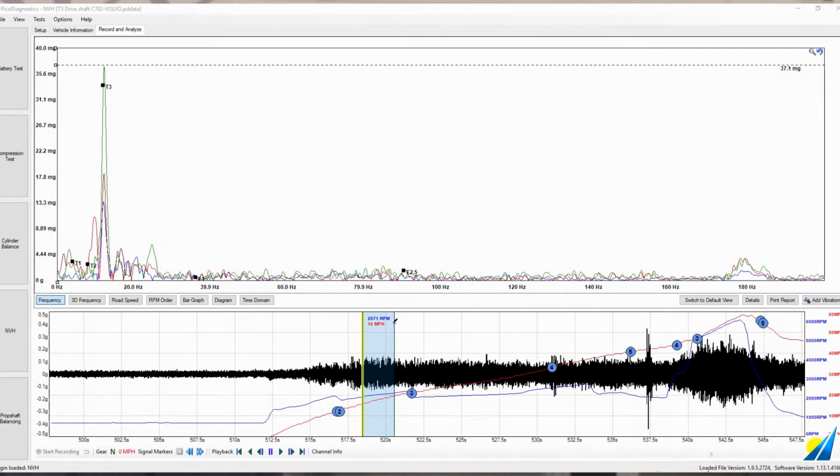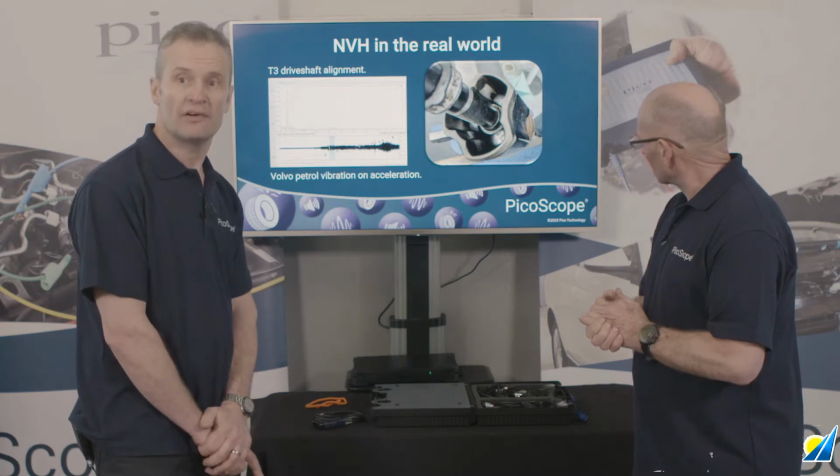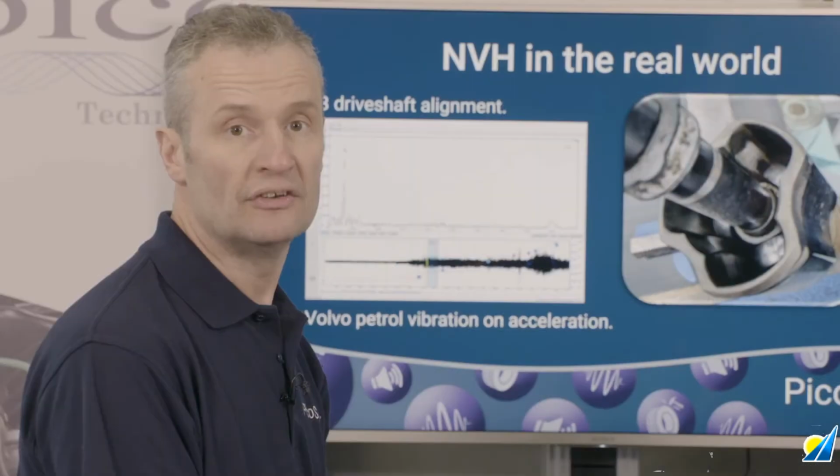The fault here was the inboard coupling of the drive shaft, so it's a tripod style joint. Now think about the fundamental frequency of this shaft, that would be the same frequency as T1, component rotating at tyre frequency, but on the thrust surface of the drive shaft we've got excessive wear. That would introduce misalignment, 3 disturbances per revolution, that gives us a T3. So it's important to think about all components rotating at what is the fundamental T1. You can see T1 there just on the left hand side of the chart. Multiply that by 3, that arrives at the same frequency as our 3 disturbances per revolution of the inboard coupling.